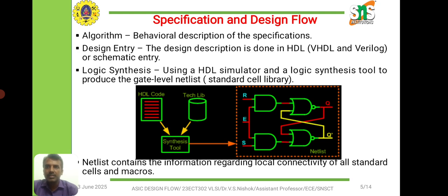And then coming to the logic synthesis. So using the synthesizing tool, the Verilog or HDL program is converted into the gate level netlist as shown in the diagram. So that netlist will be in the form of a code that represents the logical connectivity of all cells and wires between the cells. And then after converting into the netlist, post logic synthesis simulation will take place to check whether the netlist is working properly or not.